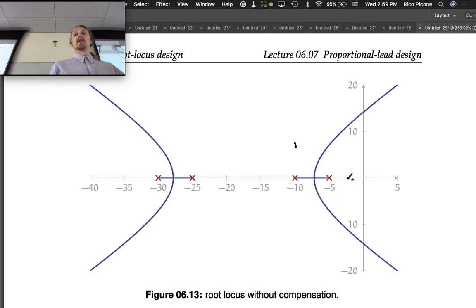And that's what happened with the case of the pole at negative 40 that corresponded to 0 at like negative 1 point something. The point that you're testing is that the real part is around 10, so the 40 will not be 5 times bigger than 10. Right, but also remember zeros being close by is problematic for us. So a 0 that's right there is really going to affect things. Yeah, so that's my main thing to think of in this case: there's a 0 coming there.